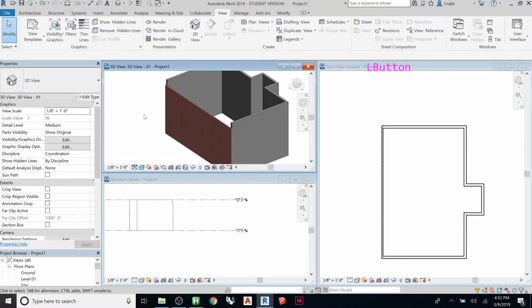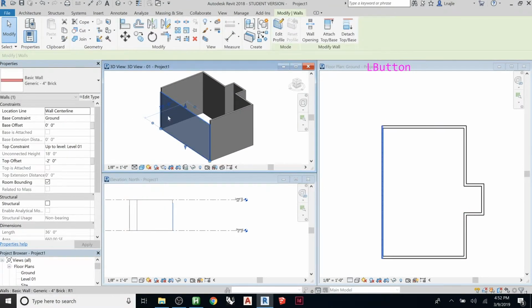It's really important to understand that because even though we changed the settings earlier, now that's a different type, so it belongs to a different family. So changes I make to that family type will only affect this type of wall. Any change you apply using any of these settings down here will affect the individual wall. And it doesn't mean these can't be the same.